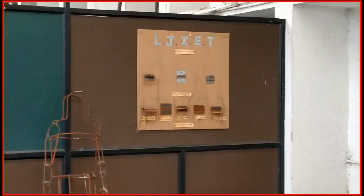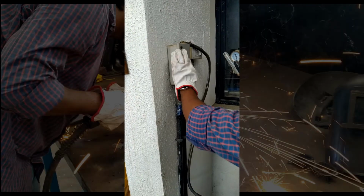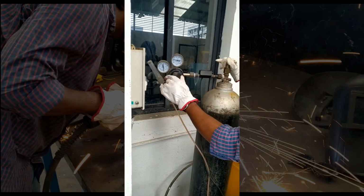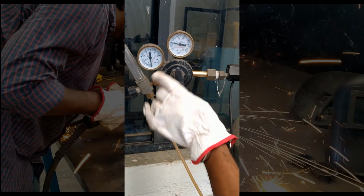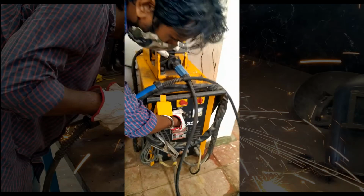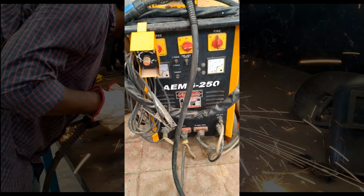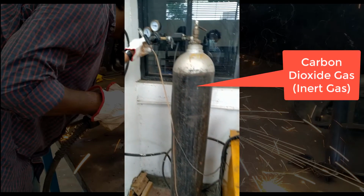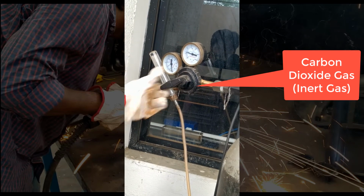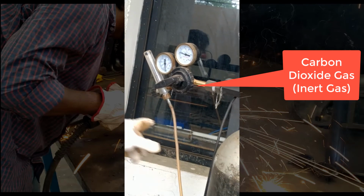So let us start our practical of the metal inert gas. These are the plates to be joined, and when we switch on our setup, as you can see, this is the carbon dioxide gas cylinder. Carbon dioxide gas can be used as an inert gas. Just by rotating the valve, and just by flowing the carbon dioxide gas, we can start our practical. Just by rotating this knob we can check the pressure and we can start our supply of inert gas, that is carbon dioxide in our case.